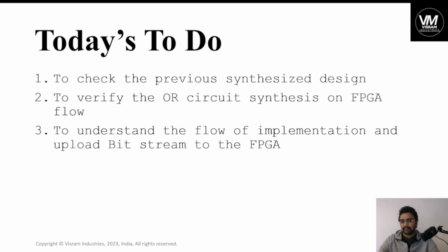It is a complete flow, I can say. There are other methodologies to develop on an FPGA, which we will discuss in later stages, but today we are going to implement the regular flow: developing the VHDL script, writing the architecture, and coming to the design implementation. After implementation, analyzing the synthesized part, simulation, and after the simulation results, bitstream generation and uploading that bitstream into the FPGA. So this is the entire flow.